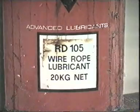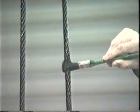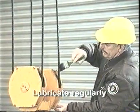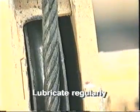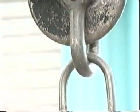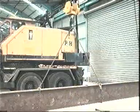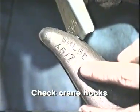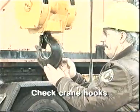Wire hoisting ropes should be cleaned and lubricated regularly to prevent corrosion, wear from friction and drying out of the core. Sheaves should also be lubricated regularly. Crane hooks should not be loaded beyond their safe working capacity. Make sure that you check the load capacity of your hooks and chains before attempting the lift.